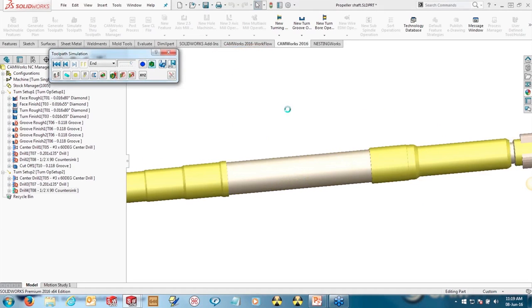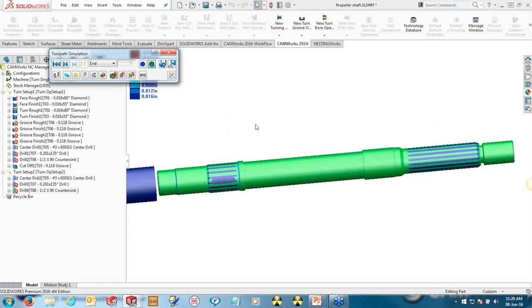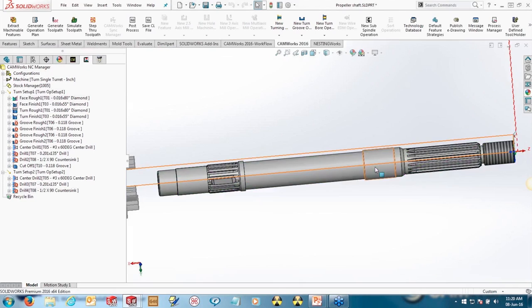So we can compare exactly and see what's being left machined. Obviously, it's not done the splines in this case. But it's got all the grooving operations here. There's maybe a little bit of material left here from maybe the tool angle, so we can maybe adjust that. But essentially, one thing it didn't do is the threads over here. So I kind of intentionally left that off here.